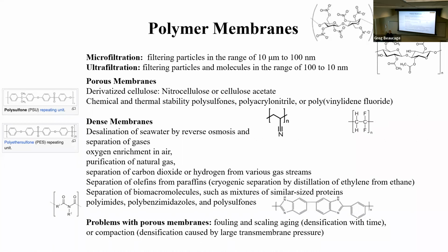So, you cool it down, you can make a liquid, and then by the different temperatures, you can take off the different cuts. But the cuts for ethylene and ethanol, you can't do it that way that well. It's really difficult to separate. So membrane separation is a way to go because there's a size difference between the two molecules.